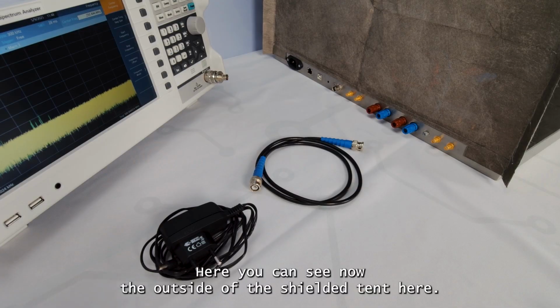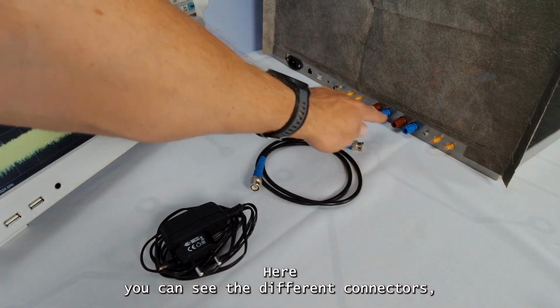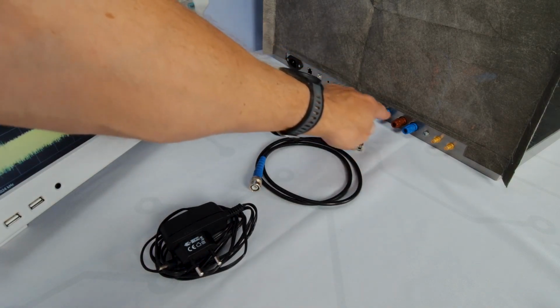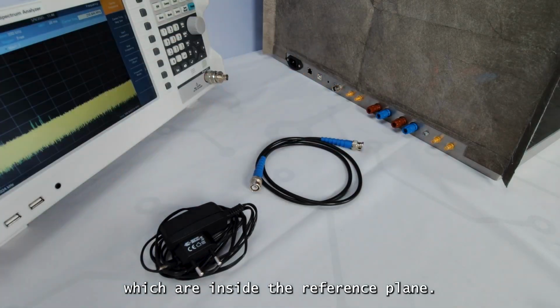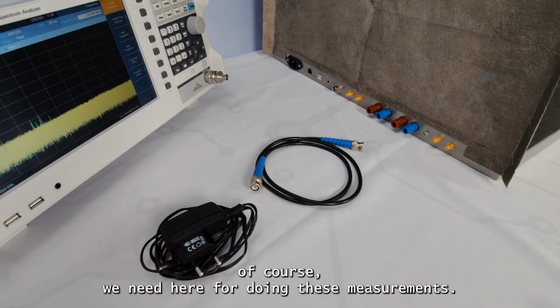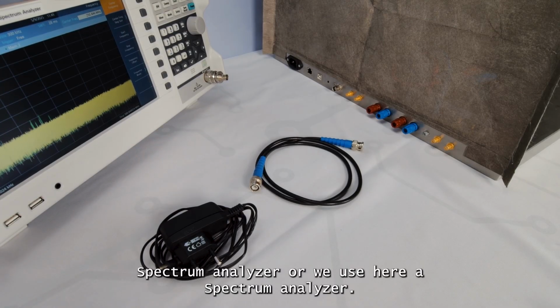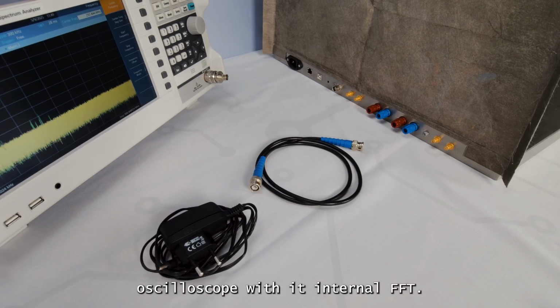Here you can see now the outside of the shielded tent. Here you can see the different connectors which are inside the reference plane. What we need for these measurements, of course, is a spectrum analyzer. You can also use, of course, a test receiver or an oscilloscope with an internal FFT.